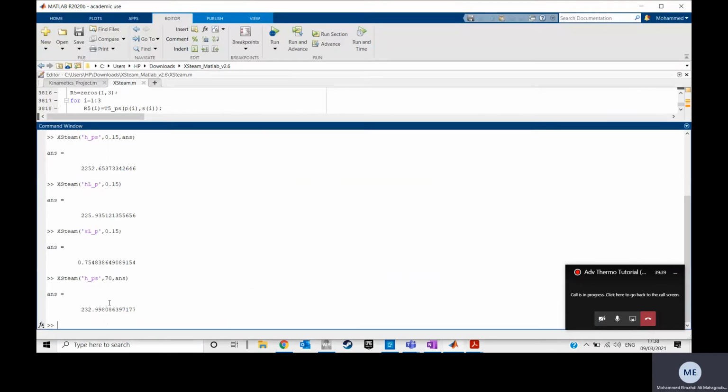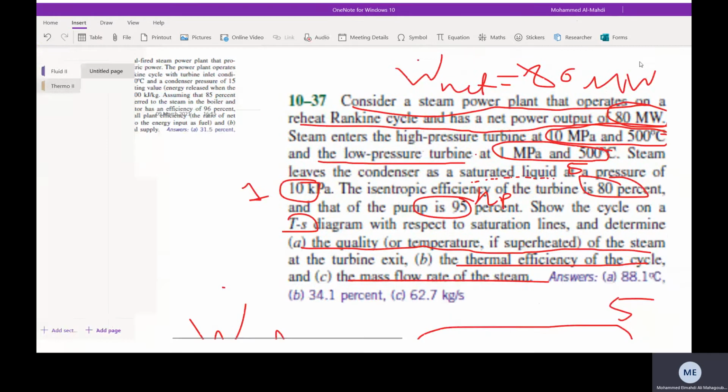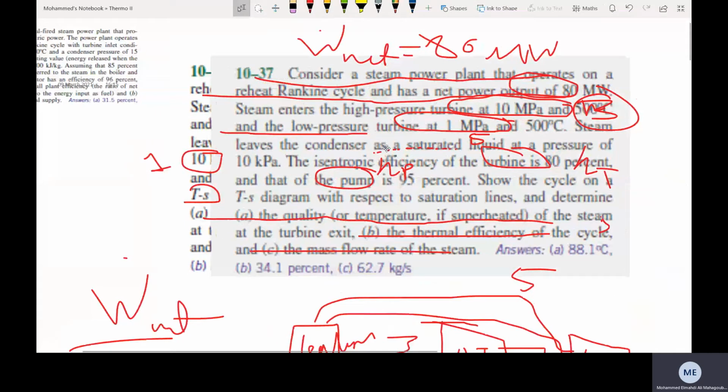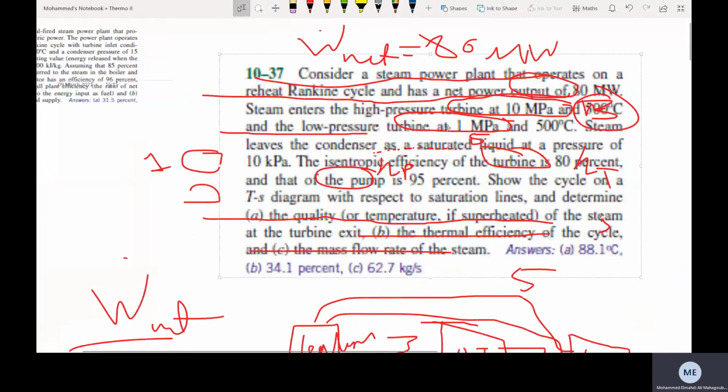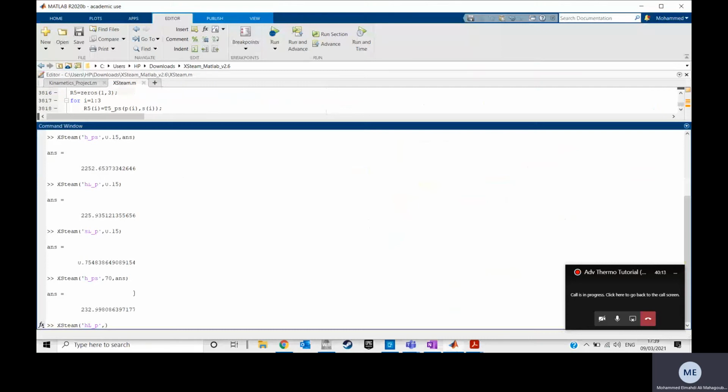What's the first thing we have? Let's calculate first for 1. So for 1, I want the H, given that I have the pressure, yes, and yeah, so I need HL, okay, from the pressure. So what was the pressure at point 1? I forgot it. Let us go to it. The pressure at point 1 was, let me enlarge it here and move it slightly so I can see it. The pressure at point 1 is 10 kilopascals. Okay, so 10 kilopascals is gonna be 0.1 bars. Okay, always make it in bars.